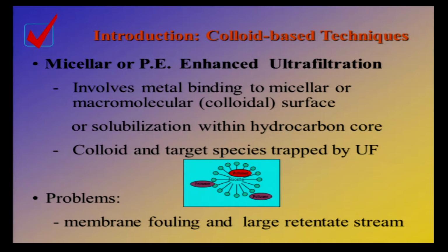So let me tell you about micellar enhanced ultrafiltration. You can see here what's going on. Remember that a micelle is a kind of colloidal particle which is formed from surfactants. The surfactants at sufficient concentration will arrange themselves in this structure where the hydrophilic head groups are outside and in contact with the water, and the hydrophobic chains point towards the center. So in the center we have something that's a little bit like an oil drop.